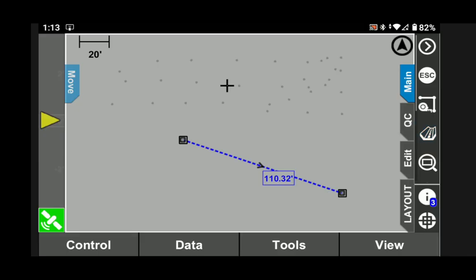We tend to call that the trench tool. You can use it to build a trench. You can use it to build a road. You can use it to build a sports field. You can do basically anything where I have a line and I want to build a profile off that line. So imagine like the center line of a road, the center line of a trench, whatever I want to do. I can just apply a profile to that grade.